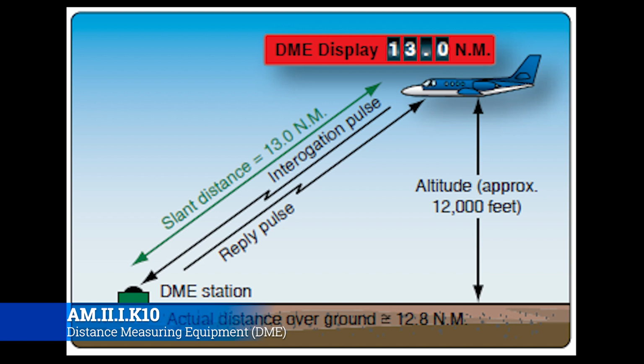And the reason why that's super important is that now we have a distance and a direction from a radio navigation aid. So if you have a DME that's integrated with the VOR, that means you could be flying and you know that you are exactly 090 from this station for sure. That's what the VOR is telling you. But with just the VOR, you don't know how far you are. You could be anywhere on that. It could be 10 feet to your left, and that's going to read the same thing, or it could be 10 miles to the left. You don't really know. But with the DME, it gives you that distance.